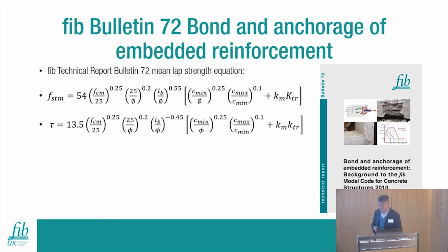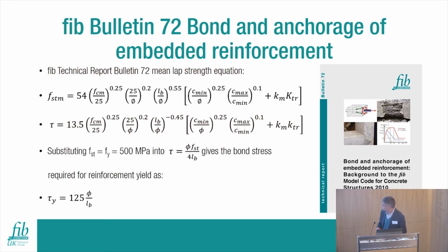So the equation for STM can be rearranged to give an expression for the average bond stress along the anchorage or lap length. I've also written at the bottom of the slide there the average bond stress corresponding to yielding of the reinforcement bar.